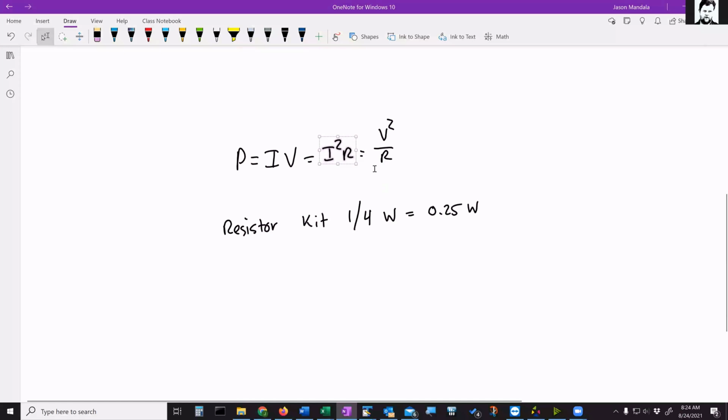So higher value resistances are going to be well below the 1/4 watt usage mostly. But when you get down into resistances of tens of ohms, or maybe 1 ohm, 2 ohms, 5 ohms, that's when you're going to get a very large amount of current, and that's when your resistors are probably going to start getting hot. So we just want to make sure you always stay under 1/4 watt of dissipation. That's the meaning there. You'd have to calculate that yourself for any given circuit.